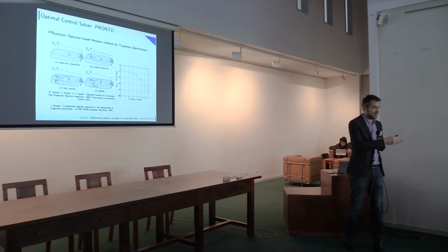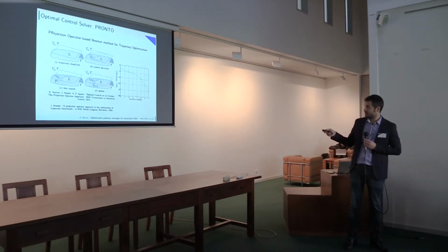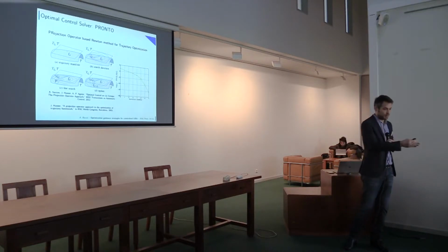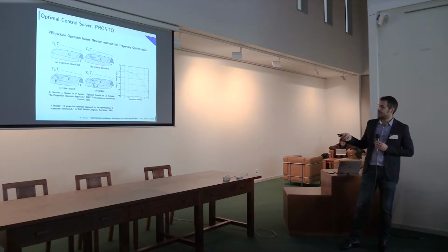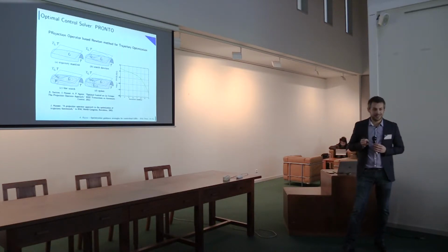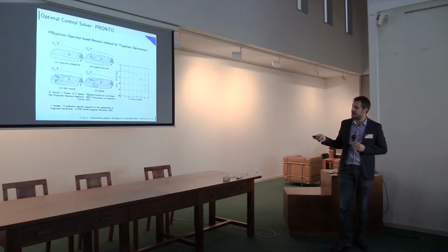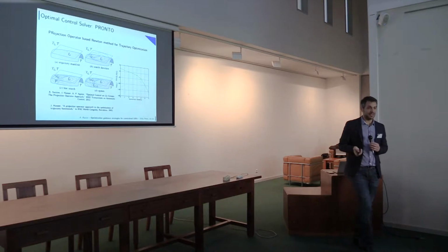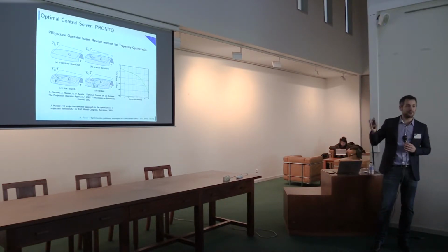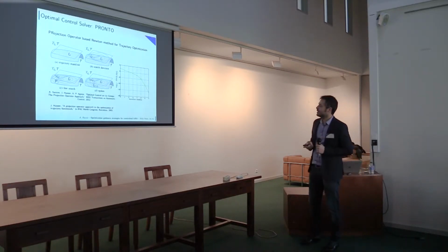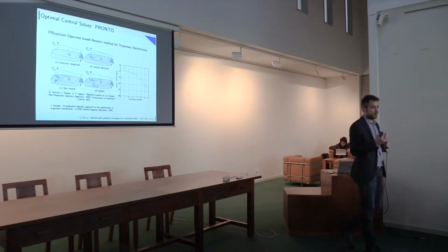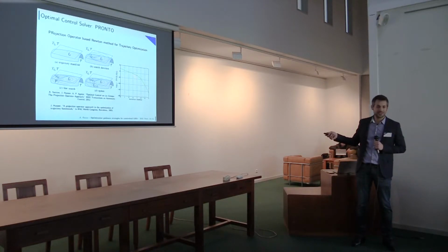What we can do now is look for a descent direction, so we want to minimize the cost functional. You see here, we look for a curve zeta i that minimizes the cost functional. Then we do a line search. We look for a gamma such that in that direction we decrease the cost functional. And then what we get, Ci plus gamma zeta i, does not satisfy the dynamics of our system. So what we can do is project, using this idea of a projection operator. Given a curve, we project and we satisfy the manifold of our system. So it's an update step. And it's interesting because when you are close to a well-defined minimum, you get a nice quadratic convergence to the optimal point, or to the optimal trajectory.